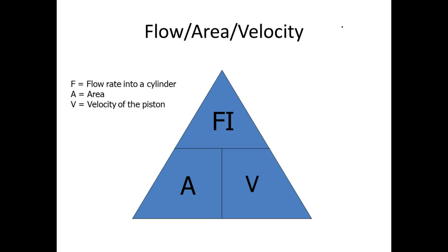That's the formula for speed. The other one is force, or what pressure is required. It's what we would use to figure out, okay, I've got this compressor or this pump that can put out 3,000 PSI, and I need to generate 5,000 pounds of force. What size cylinder do I need? Then you could use that. You can transpose it. If you know what force you need and the area of your cylinders, you can calculate how much pressure you need, or vice versa. If you know your pressure and how much you're trying to move, then you could calculate the cylinder you need.